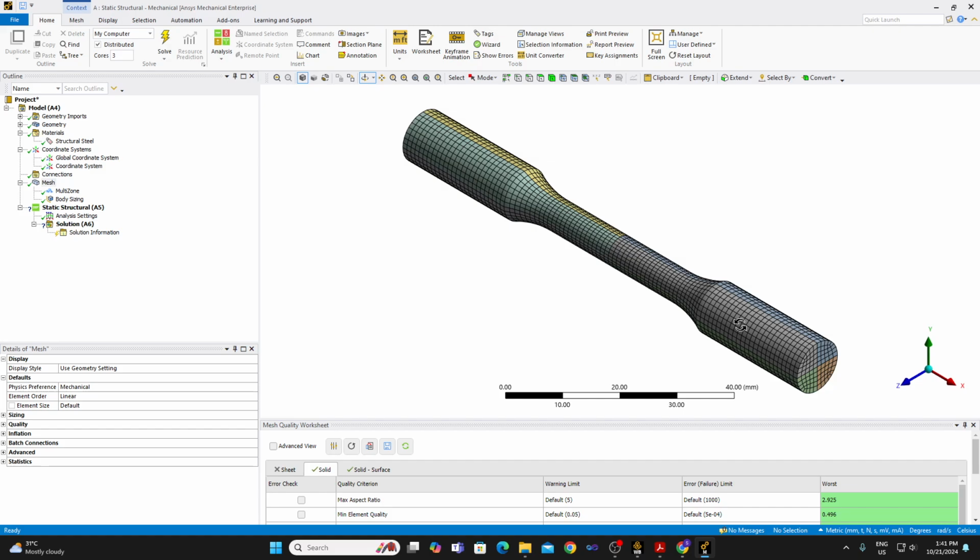So there is no need for resolving that region, because not a lot of elongation is going to happen there. There is no need for having that region resolved with a huge number of elements. You need the majority of the elements in the middle.